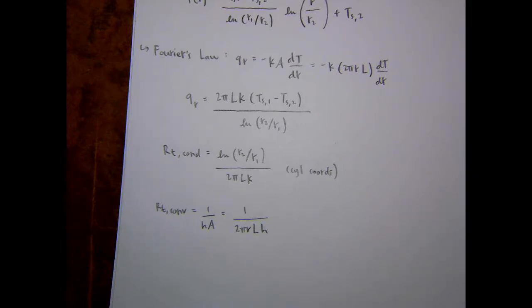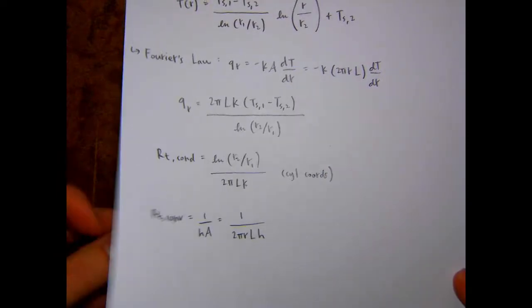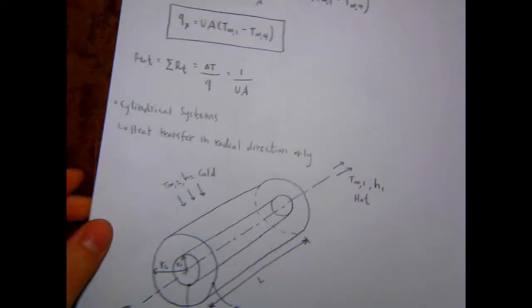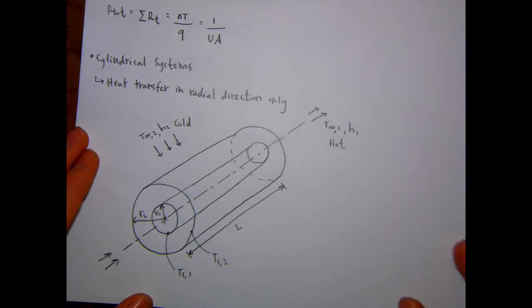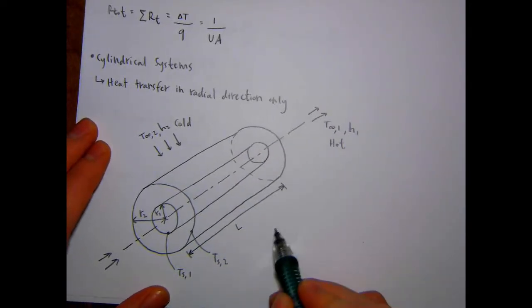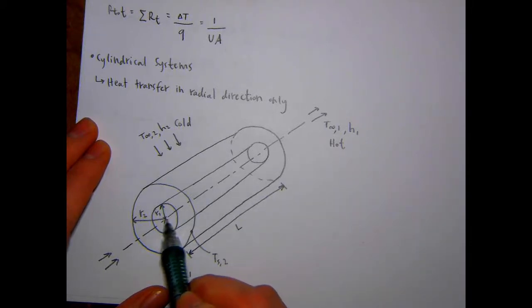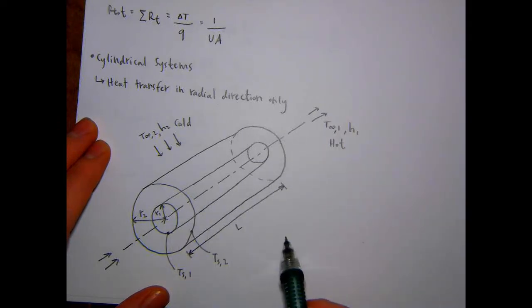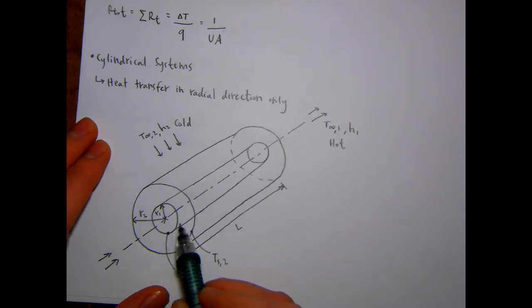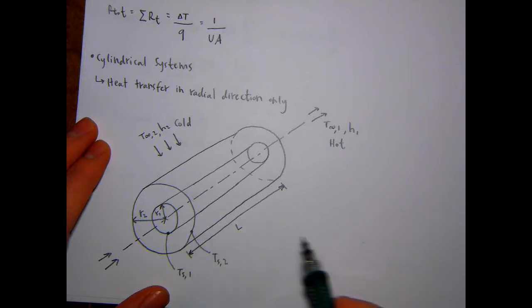So let's try to write down the thermal circuit for this cylinder. So we'll go back to the drawing. And remember, this was just a way of visualizing the temperature at each different location radially, or in the x direction, depending on your coordinate system, and then what the resistance is for the heat transfer between those two temperatures.